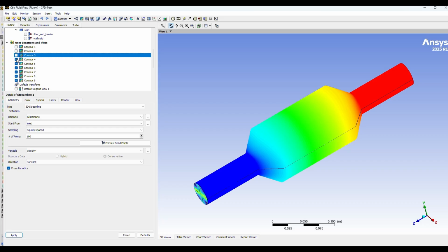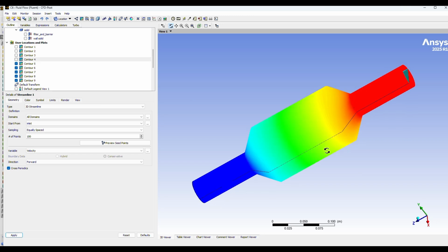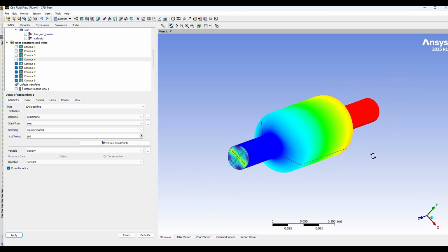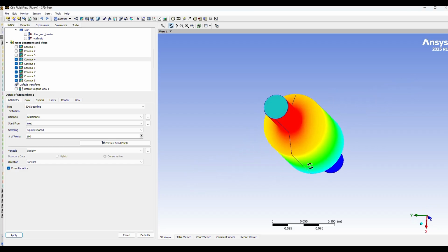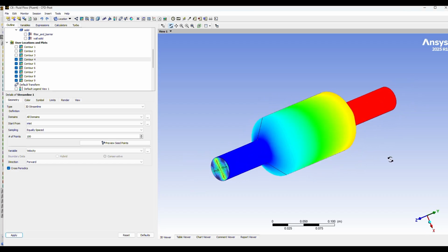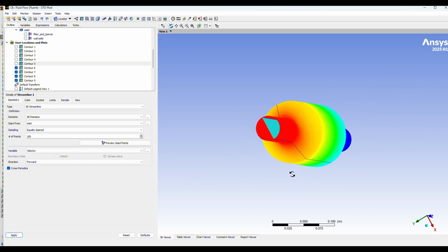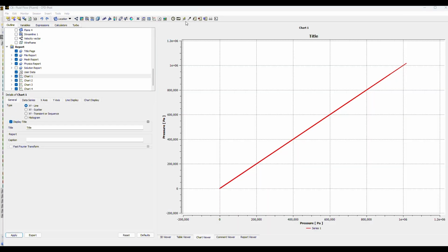So this is my second figure where I modified the geometry at the center to act as a barrier layer for the inlet, and checking out what are the pressure contours, velocity contours, and the turbulence kinetic energy at the outlet.